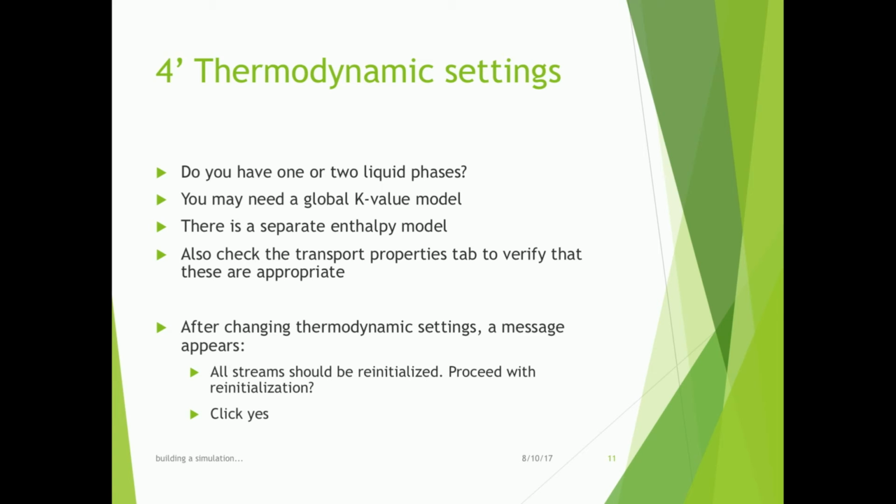When you are ready to run, before you hit the run button, it will ask you, are you ready to change the thermodynamics section? It will reinitialize the problem. Basically what it does is flashes with the new thermodynamics on all the streams going into or out of the process as a way to start. That lets it start on a basis for which it can usually find a solution.